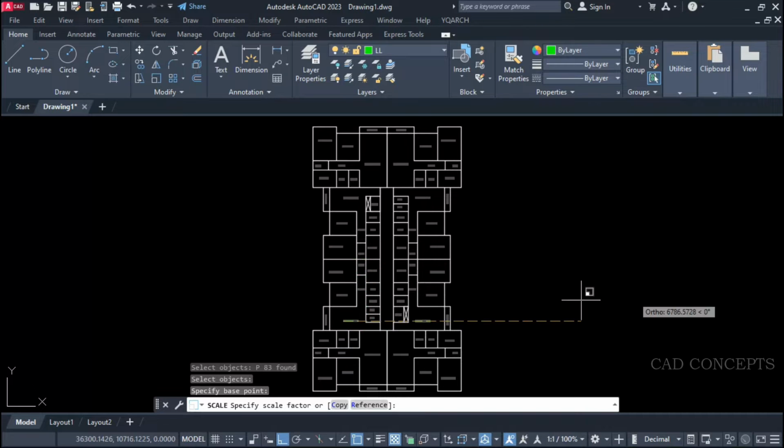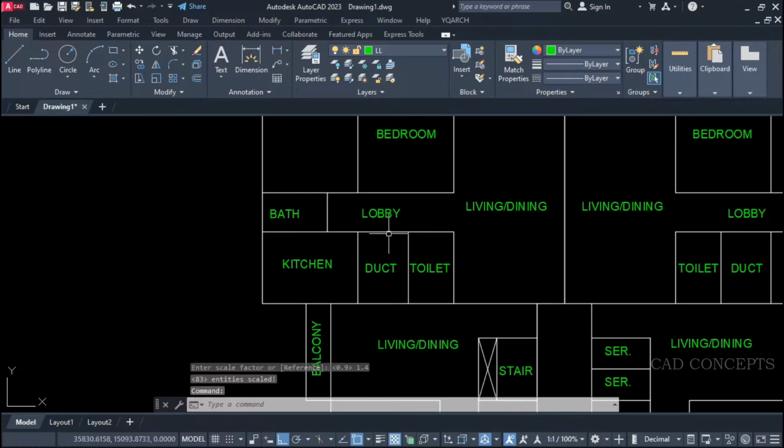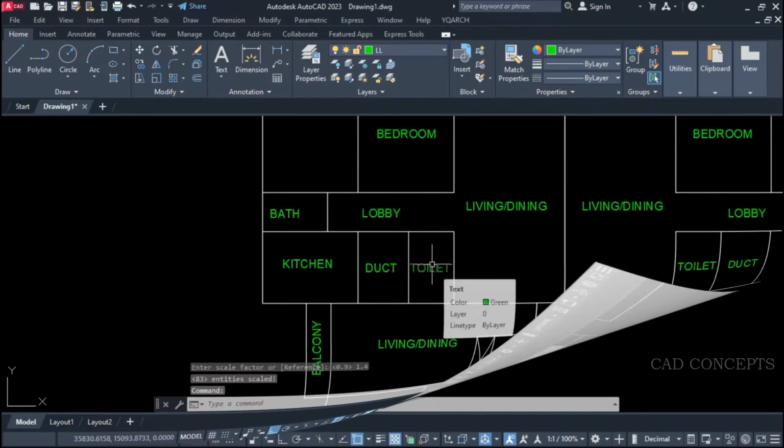If you see here, if you will scale default, so it will go all with center point. With a reference, it will go all. But if I will take ASC command and to the point, it will scale each text at a time. As you see here, something like this. So this way directly you can scale any object, multiple object, center to center, something like this in just one time.